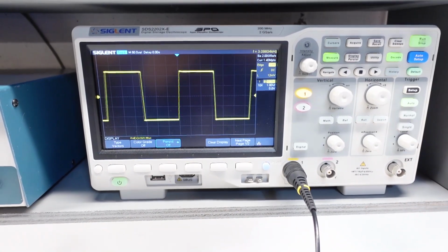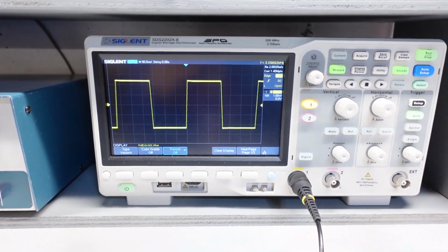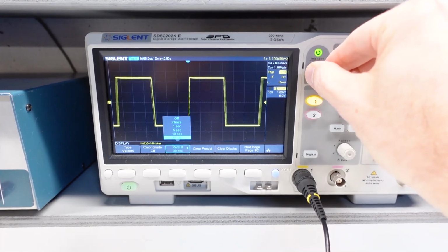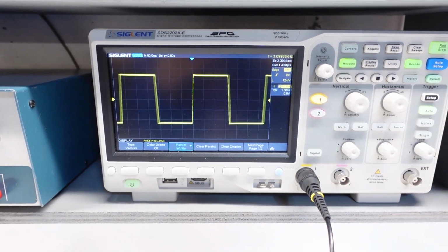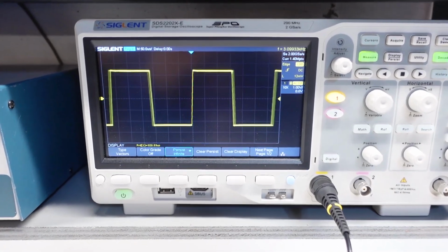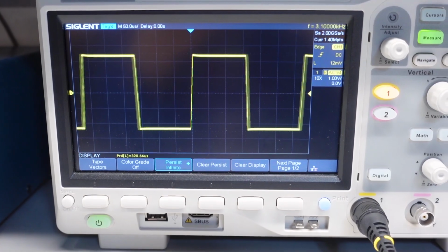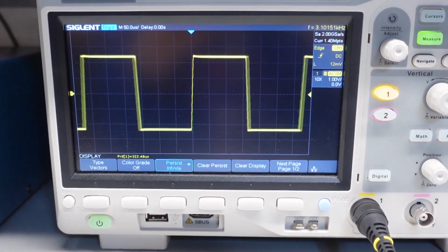I was also seeing a lot of jitter on the output. You can see it here on the scope. That made me really nervous because if I truly were topped out at about 8 kHz, then this jitter was certainly a concern for the quality of the conversion. Maybe I could solve this issue, but after burning more hours than I care to admit, I shelved this idea for now and instead went back to the PWM to audio approach.